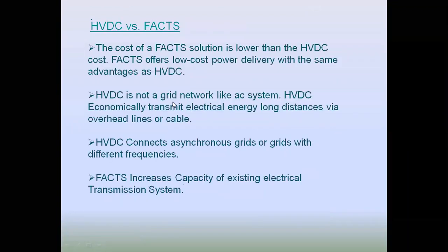We have compared this with HVDC technology, because both are competing technologies. In some places FACTS are useful, and in other places HVDC is an advantage. Since we use FACTS technology on the existing system, the cost of the FACTS solution is lower than HVDC, because in the case of HVDC we require converters.